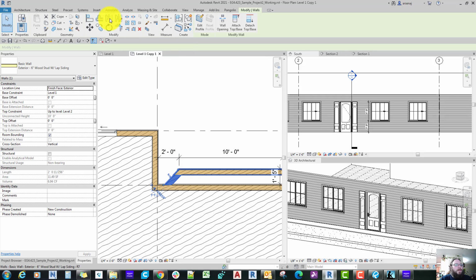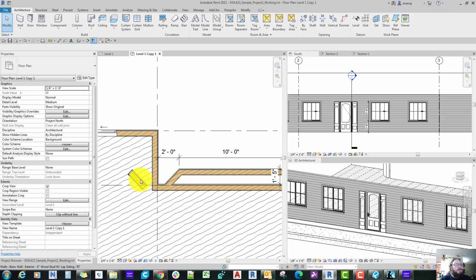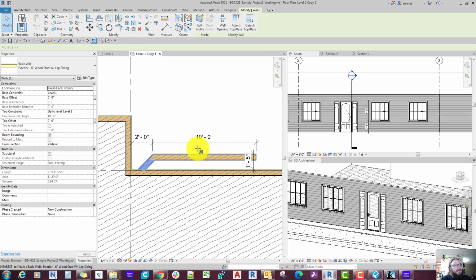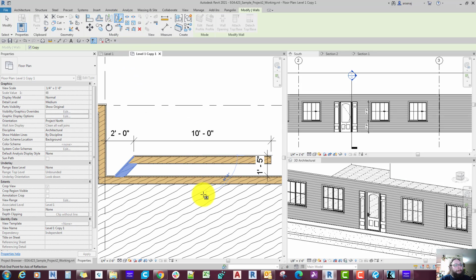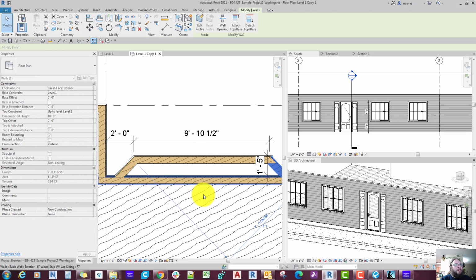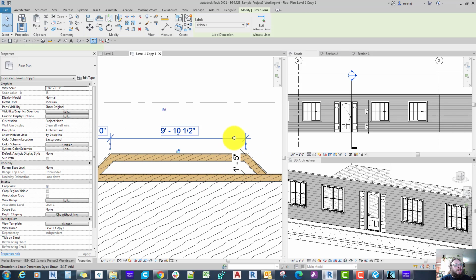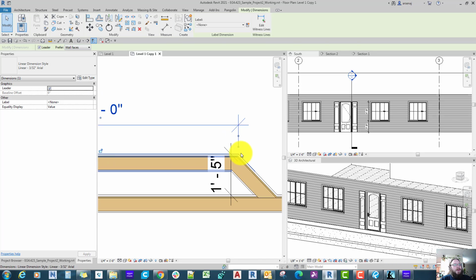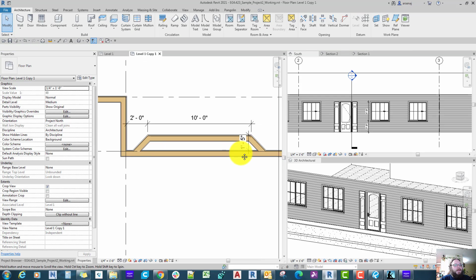So if I wanted to mirror across this wall, I would pick this axis to mirror, but on this I wanted the center line of this 10 foot, so I'm going to draw my own axis. And you can see it placed it there. But it's good in my dimension over to be the center of these intersections. And so I'm going to move it over there just to make sure I still got my 10 feet. And I do.